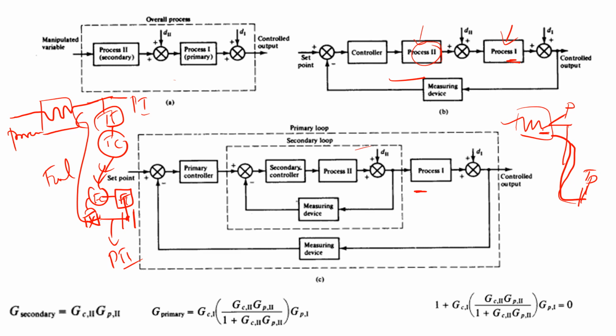For this, who gives the controller set point? From the primary controller. So this is the primary controller. It gives a set point, and then this gives a process variable. Then the error is given to the controller. Once it is controlled, it will affect the process. Okay, so this is process one. For the process, we use the measuring devices. So this is your TT, this is your FT, this is your FC, and this is your temperature controller.